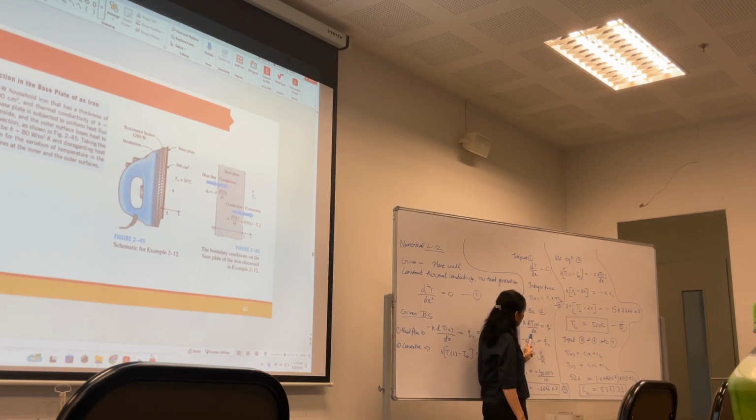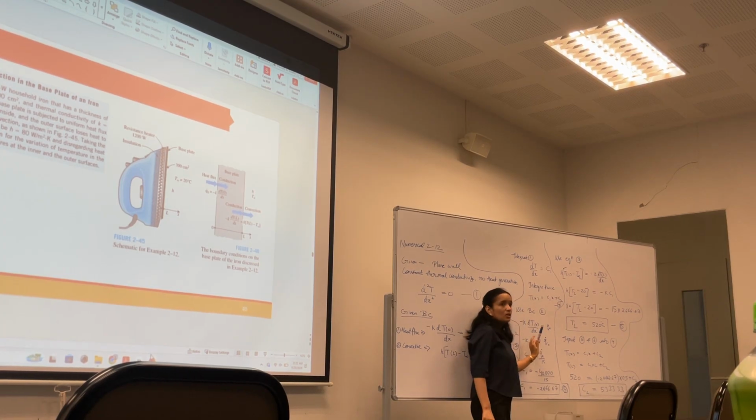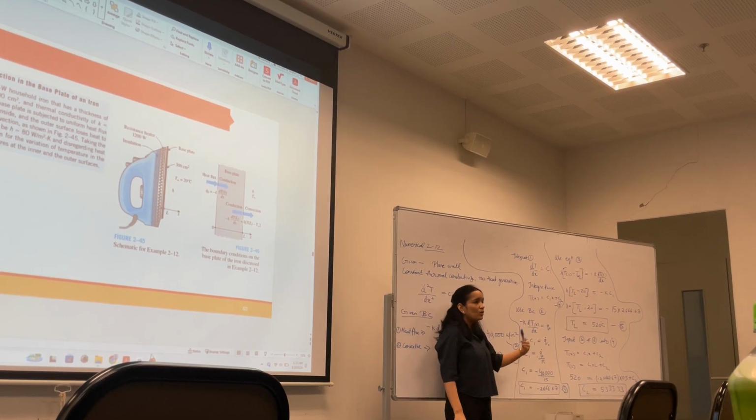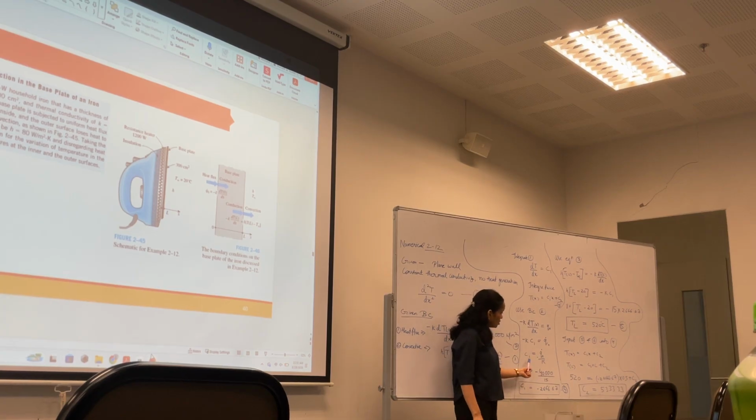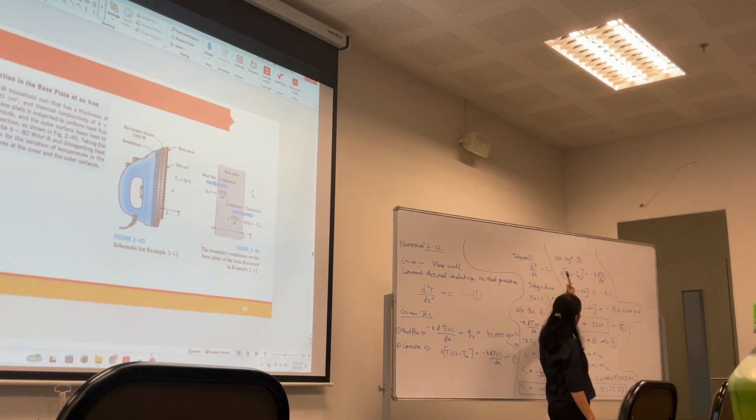So you utilize this boundary condition, heat flux. Okay? Input C1 here, this everything is given. In your book, they are doing it in different way. So you can follow that or you can follow this. Either way is fine. So you have the value of C1. Alright? Then you use the convective boundary condition, input everything, you get the value of Tn.